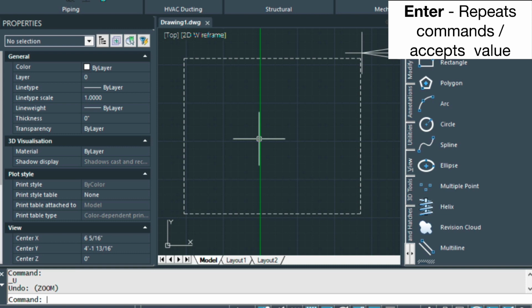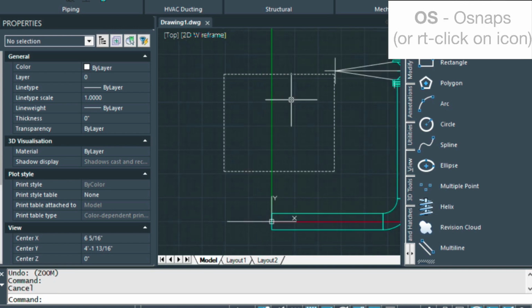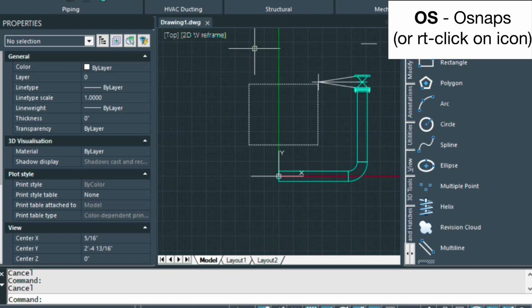So in CAD, all those steps are being kept track of, every single step, whether it be an erase, copy, zoom. Those are all undoable by pressing U and then enter. Immediately after the last command, if you press enter, you will fire up that exact command over again without actually having to retype it. Now I'm going to change gears a little bit and talk about dimensioning and also dim scale.